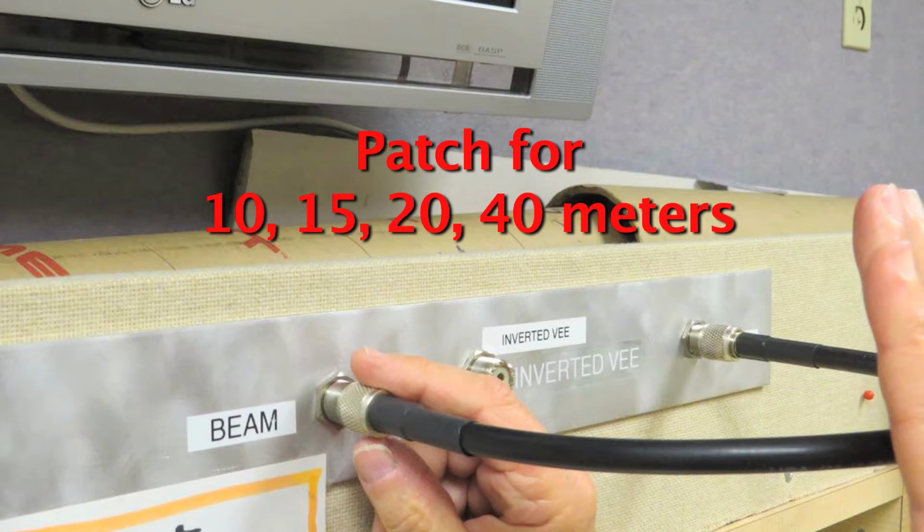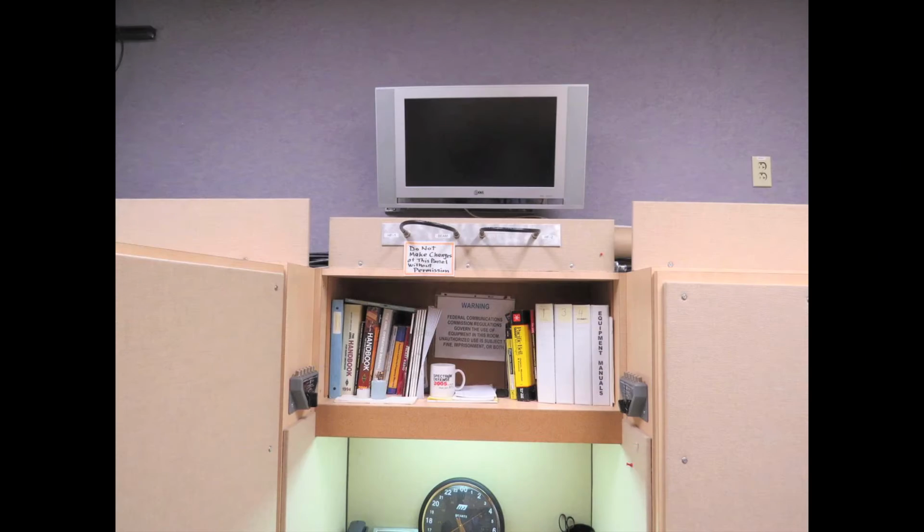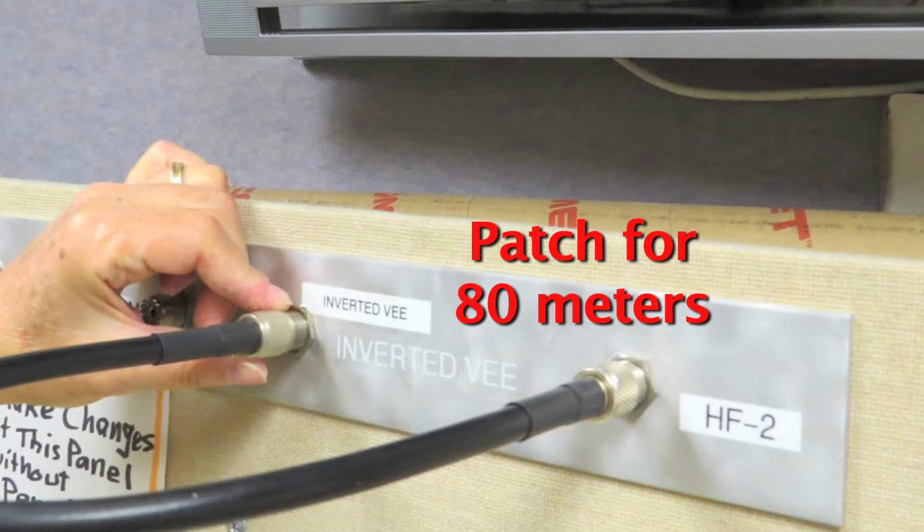If you're operating on the 10 to 40 meter bands, be sure the coax is connected by Kaiser's coax jumper to the 10 to 40 meter beam connector. That is located on the panel high up in the middle of the radio room. If you're using 80 meters, that jumper must be moved to connect to the 80 meter, that is the inverted V coax connector, and back again when you are finished using 80 meters.